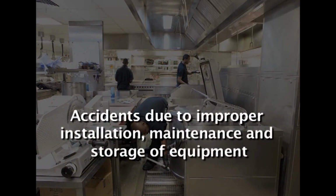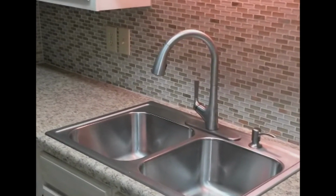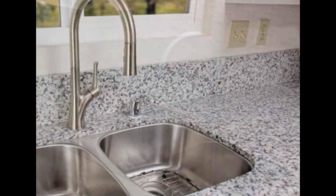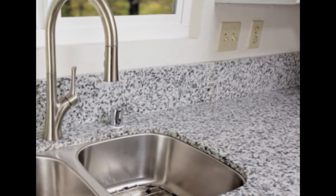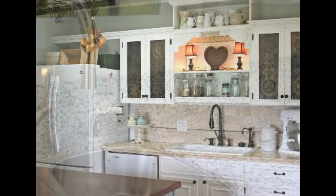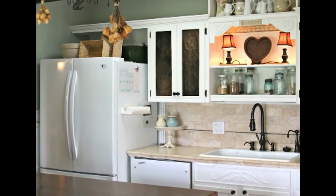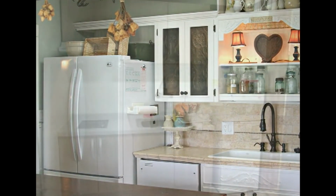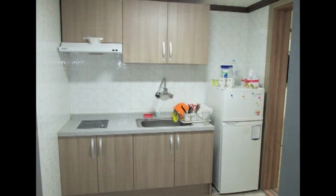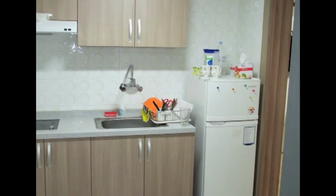And next is accidents due to improper installation, maintenance and storage of equipment. Improper installation is, as I said, while you are placing sinks, it is always advisable not to place sockets or plug points above those sinks, because water spillage can occur. And another aspect is you cannot keep bigger equipment next to the sinks, because water can fall into that equipment, and again an electric short circuit can occur, equipment can be spoiled, and work will be hindered. So these things need to be definitely considered.